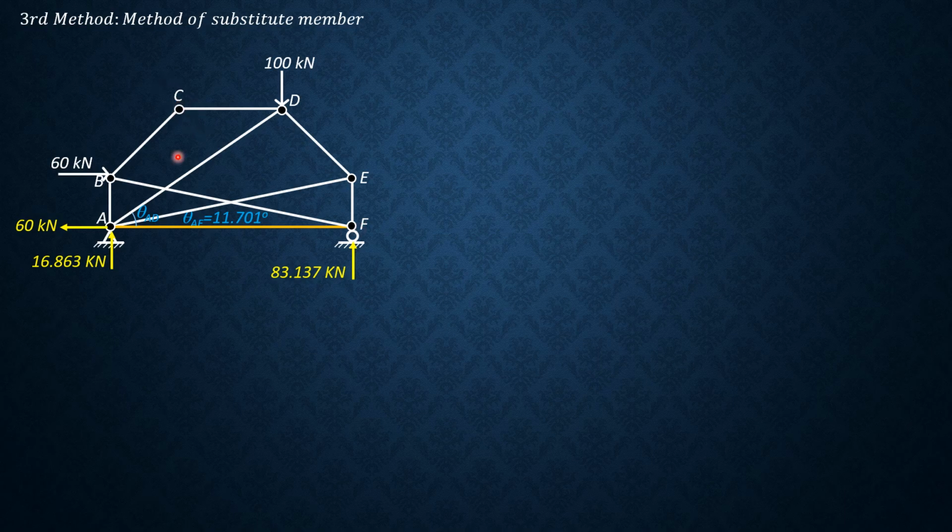If all the joints have loads, then you have nothing to do. You have to transfer it to another member, and you have to solve for the forces remaining in that joint. So it consists of two phases. In the first phase, we have to solve for the forces of all these members left. Then in the second phase, we apply the force in CF so that all other members can be expressed in terms of that force in CF.